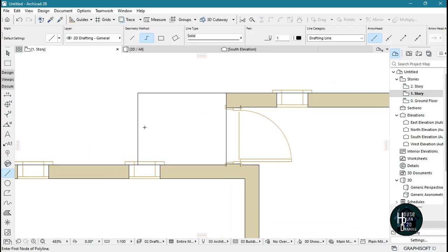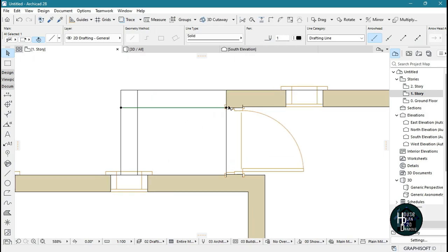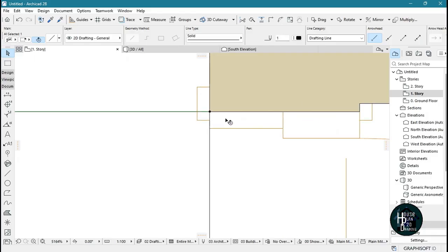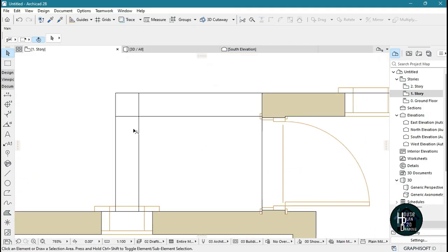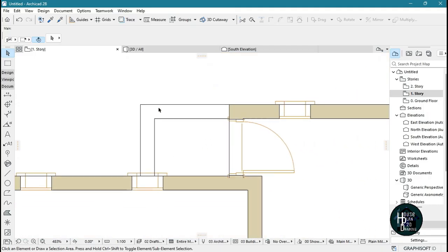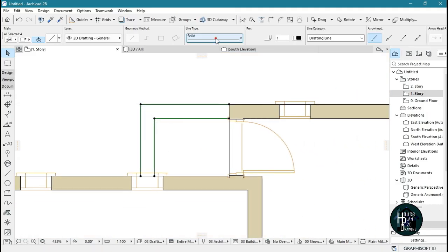Okay, so I've done that. I'm going to click on this line, press Ctrl Shift D, and let's make a copy by giving a copy distance of 225. Click enter, click this, Ctrl Shift D, and let's give a distance of 225. Okay, just make sure it's actually 225. Okay, all right, so I'm going to cut out the space, highlight all of this, and let's change it to be a dash small.